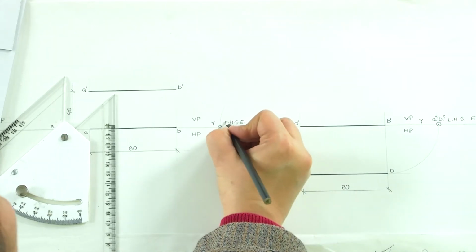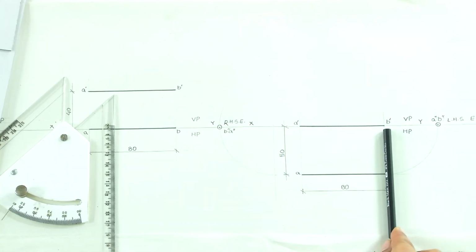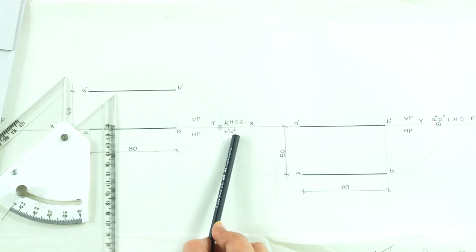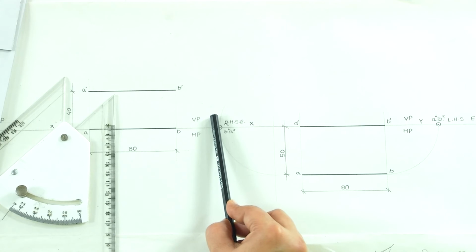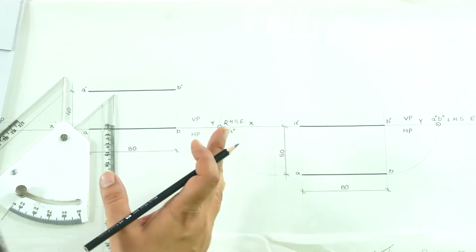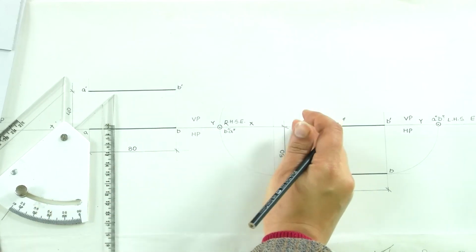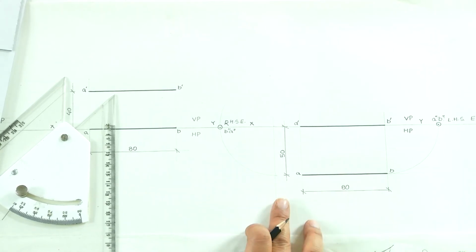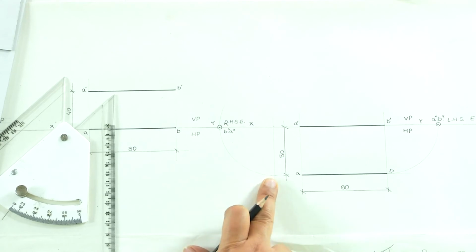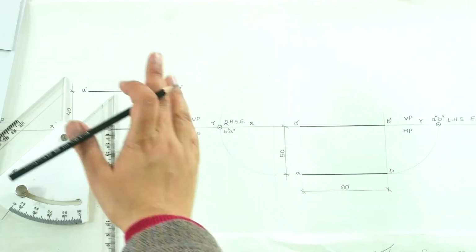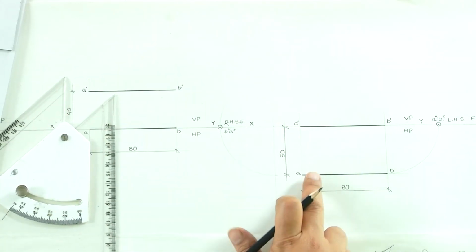Sorry, this is the right hand side elevation. So, we are seeing it from the right hand side and it is drawn on the left hand side, and what we see first is this point B. So, B double dash, A double dash, and this is the right hand side elevation drawn on the left hand side, and this projection screen on the side is starting slightly away. It is not mandatory, it is not even required to mention the distance. The only thing we need to know is that from where the projection screen is opening onto the elevation screen, we have to take the projection lines straight.